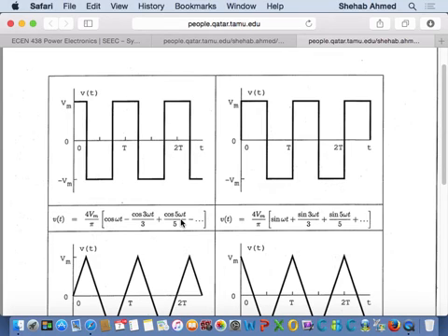So you can approximately tell me, okay, because this is going all the way to infinity, at some point you have to stop. You cannot go to infinity. And when do you stop? At some point, these numbers become very big. So if you take a number divided by a number that's very big, the magnitude becomes irrelevant. At some point, the amount of power that's being transferred by the source at higher frequency is going to become irrelevant. But if you want a 100% exact solution, then yes, you have to go all the way to infinity, take all these components and calculate the power due to each of them, right?